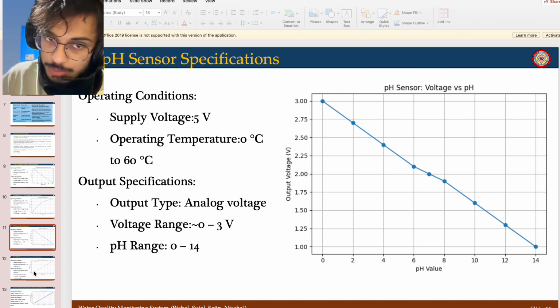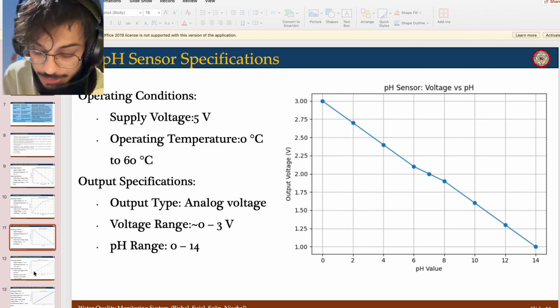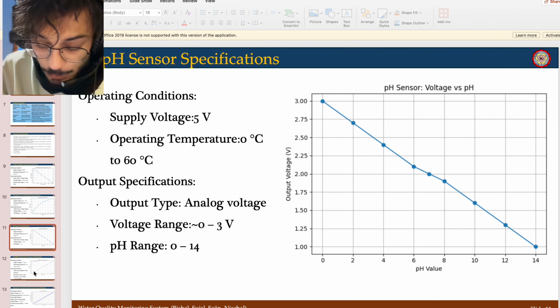Let's assume the reference voltage is 100 millivolt, and the operating voltage range is minus 414 millivolt to 414 millivolt. That voltage range is converted to 0 to 3 volt by signal conditioning, which will be done by the signal conditioning module that comes with the pH sensor.